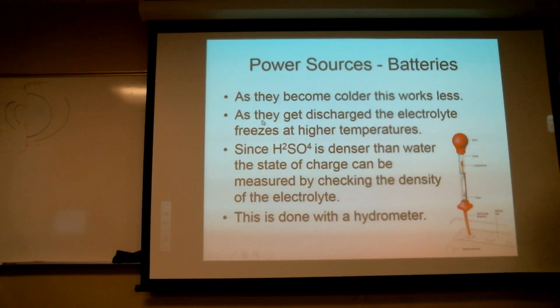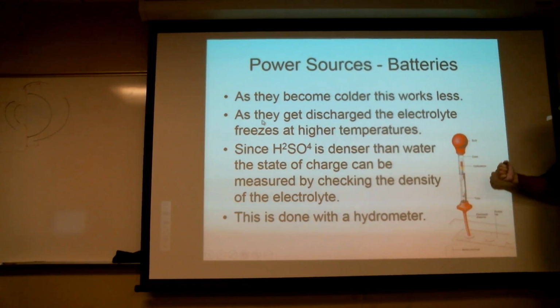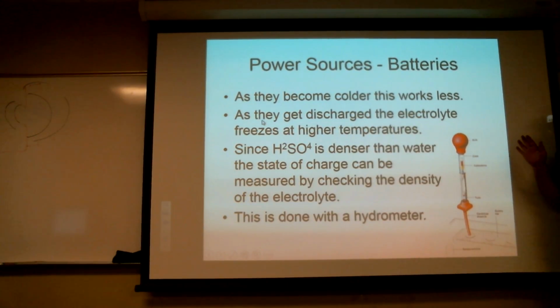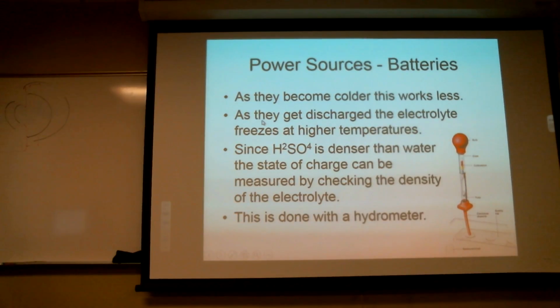Okay? So you pull the battery out. Check the specific gravity. Oh, yeah, it's all low. And in fact, I open them, there's a bunch of gunk, yucky in there. From the get-go, you're going to then say, that cell might be bad. That cell might be shorted. I don't think any of the ones that we have here are shorted. One of them might be.